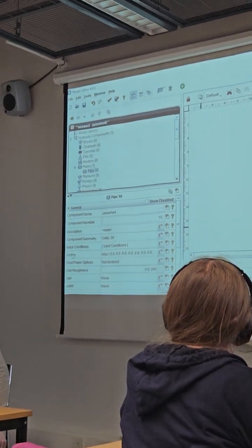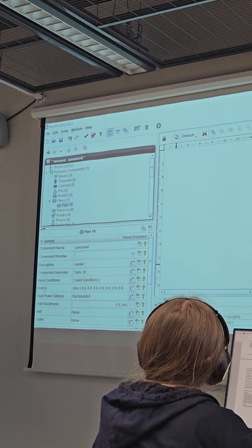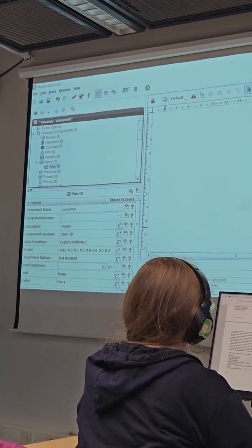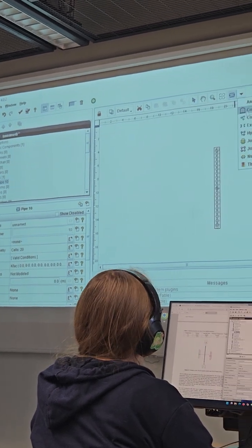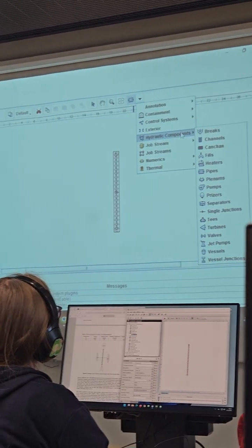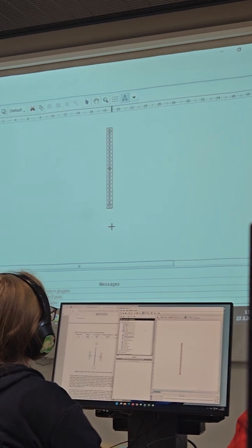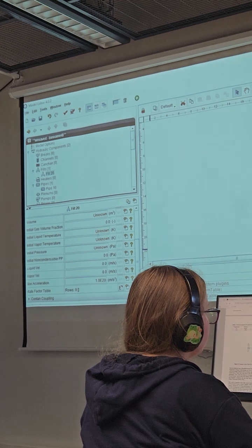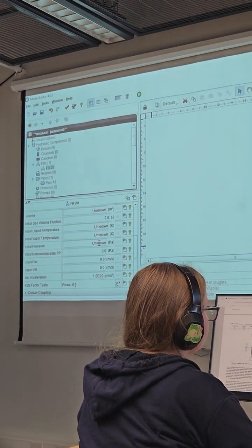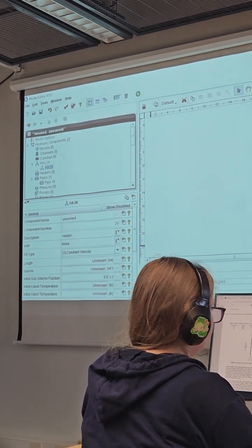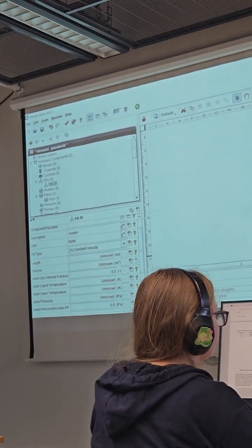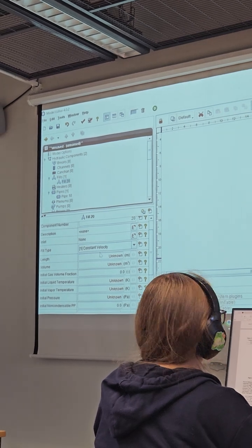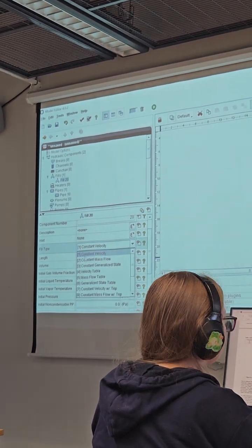For the pipe, the next part will be to create the fill and break components. It is an inlet and outlet respectively. We just need to go to the hydraulic components and then choose the fill. There are a lot of unknowns we will have to define, but most of them are given in the assignment instruction. We just need to change the fill type to the constant mass flow. It is the second option.